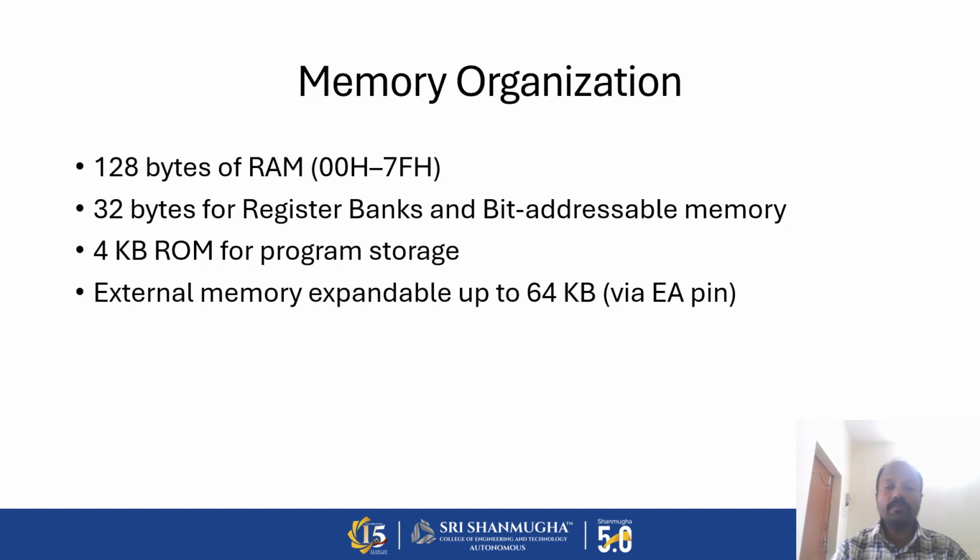We can work with different registers using the CPU, which is considered the main part of the microcontroller. This is about the memory organization of the 8051. We have 128 bytes of RAM, addressed from 00 to 7FH, and 32 bytes of it are for register banks and bit addressable memory. We have 4 kilobytes of ROM for storing the program. External memory is expandable up to 64 kilobytes. Using the EA pin, that is the external access enable pin, we can access the external memory.